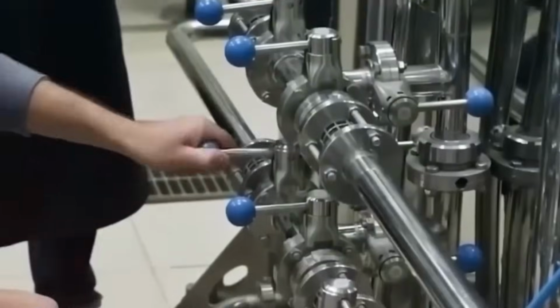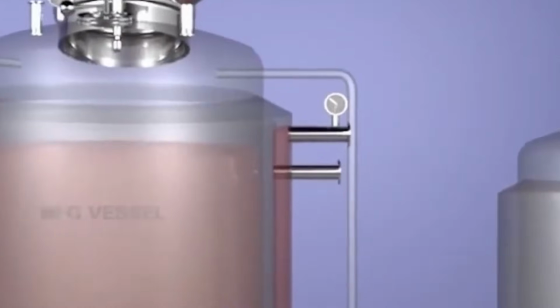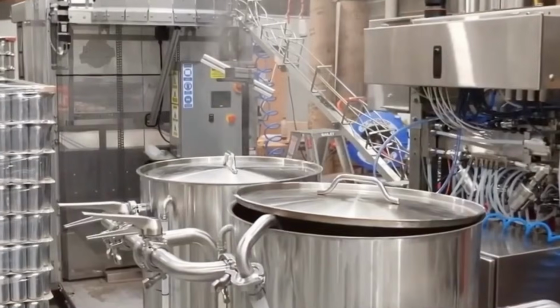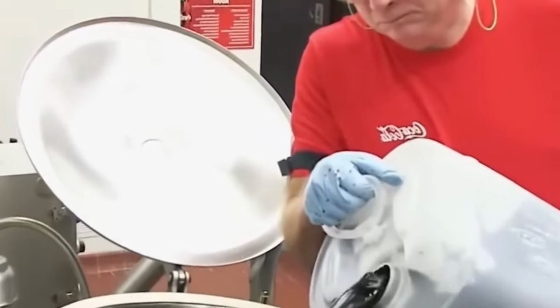For cans, ends are placed on top by an end-feeding chute, and a seaming head curls the lid over the rim in a multi-stage process to form a hermetic seal. Once sealed, the containers pass through a pressurized water spray or vacuum chamber to remove any residual product from the exterior. The sealed containers move toward quality assurance.